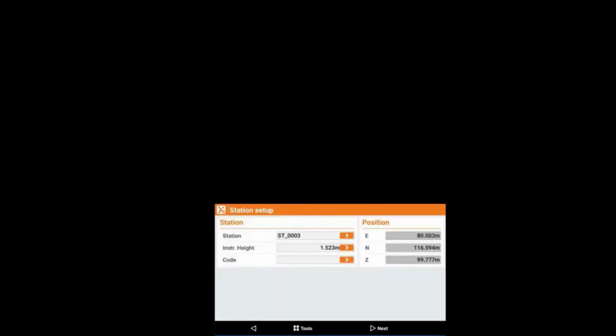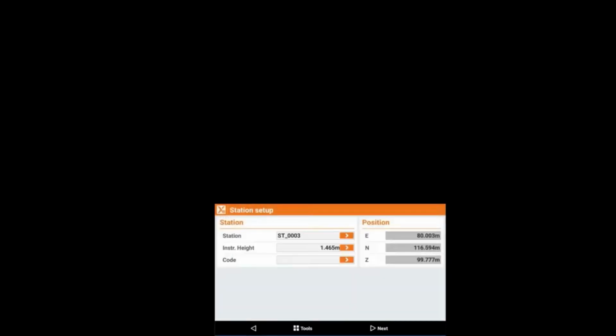We position the prism on the station number 2. I can say yes, move to the station number 3. And in that case, again, I need to enter the elevation from a slant height, and now select the slant height of the point. Choose 1.468. Okay, accept it. Automatically the elevation difference is calculated between the target, the ground prism, and the TPS height.